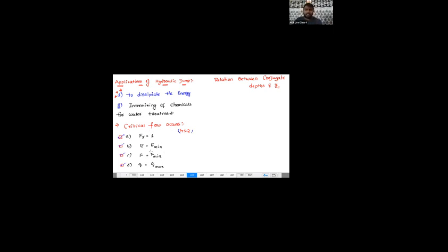In all these conditions, whenever you see this condition, if I say Froude number is 1, then the energy is minimum, force is minimum, discharge is maximum. If I say discharge is maximum, energy is minimum, force is minimum, Froude number is equal to 1. So critical flow occurs in all the cases, and in all the cases the depths are going to be the same. Keep that in your mind.